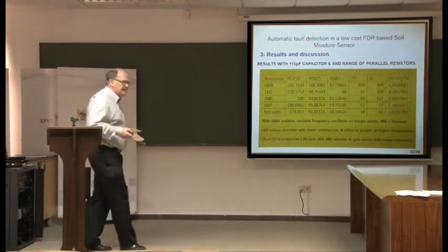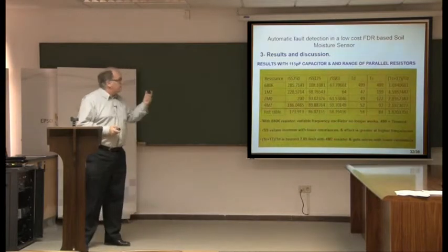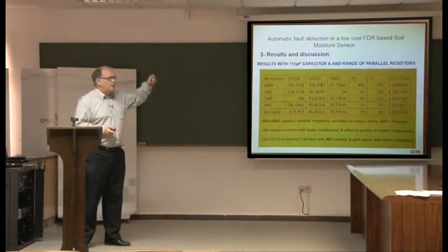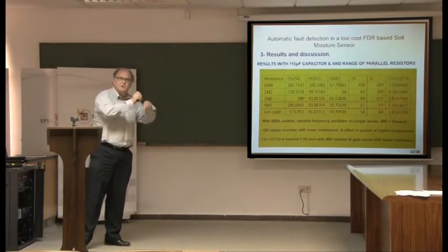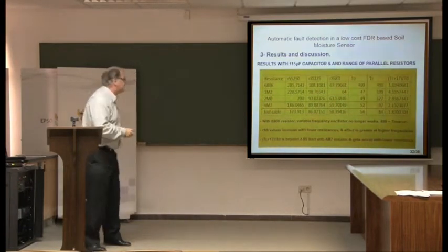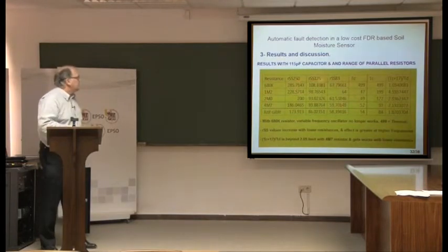Now to simulate damage to that sensor, we went back to the capacitors and we put a resistor in parallel with them. So this represents a scratch or some form of damage to that sensor. You can now see that when we just had the cable connected, these are the values for the reciprocal signal strength, the time to discharge, the time to charge, and again our number here is in our magic range of 1.75 to 2.05.